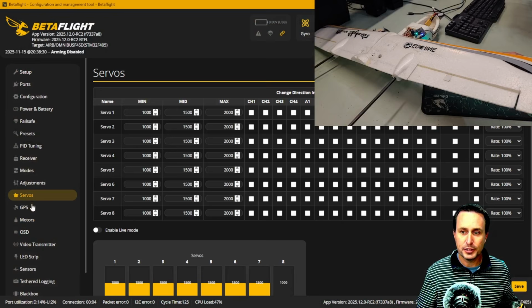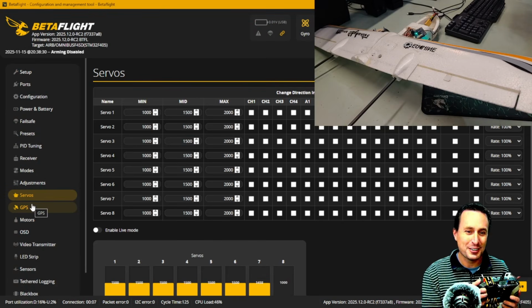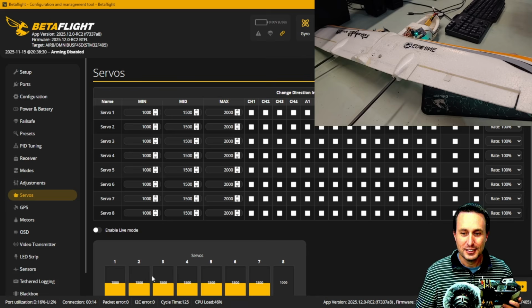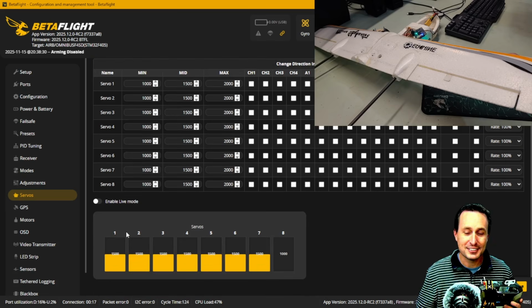There's some other things you can do by going into just the servo output here. And it's a little weird because of the servo numbering. So like this 4 is actually 2. So 2 of these here, I guess, are motor 1, motor 2. So this is servo 1, 2, 3, 4, 5. Since this is motor 1, motor 2, as in that airplane diagram, then again, servo 1, 2, 3, 4, 5.